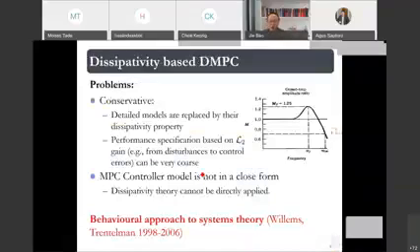However, when we tried to extend those results to MPC, a distributed MPC, we had problems. Number one, as I said just now, the whole idea is that we represent the properties of each subsystem using its dissipativity. But the dissipativity property can be very conservative. For example, we know we can have an output feedback passivity condition that represents the L2 gain. I can have the L2 gain of the plant-wide system from the disturbance to the process output.